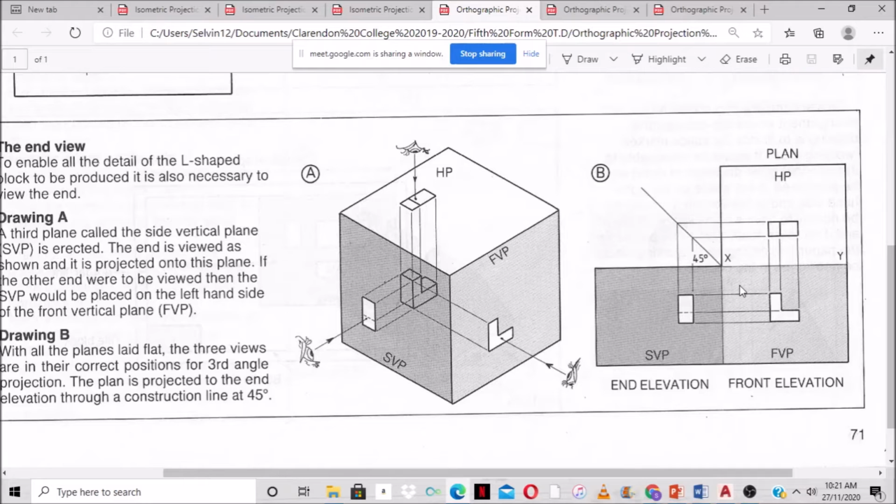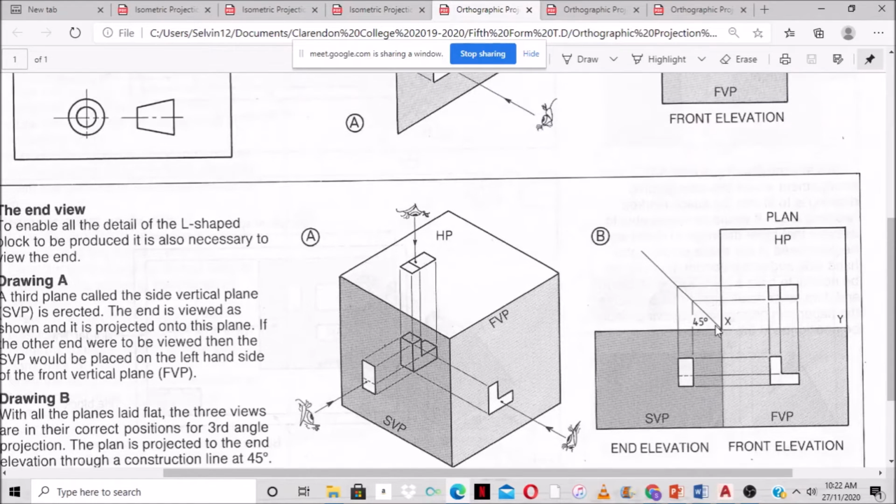As you can see, in order to project these lines, they are drawn at a 45-degree angle here. So from the highest point here, you draw a 45-degree angle, right? Or you can go 1 millimeter or 10 millimeters above this joint, and then you project a 45-degree angle. You follow? And then where these intersect now, you will bring these up to this here. Follow? Yes, sir.